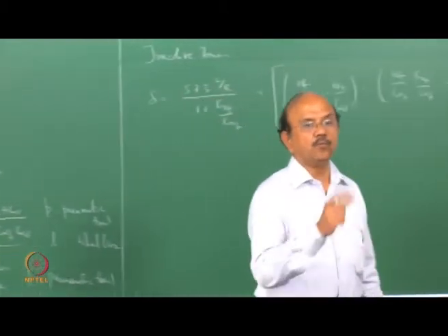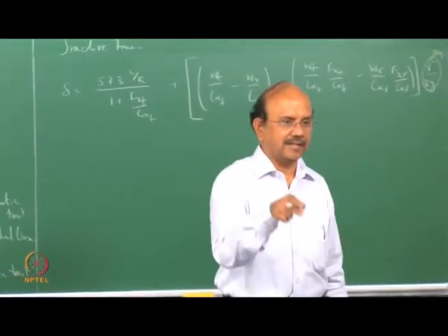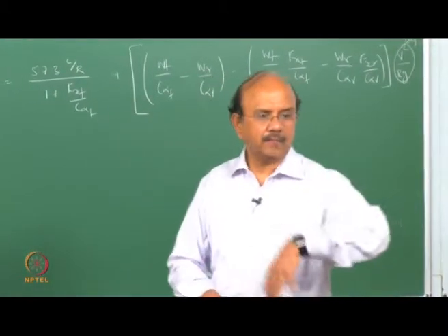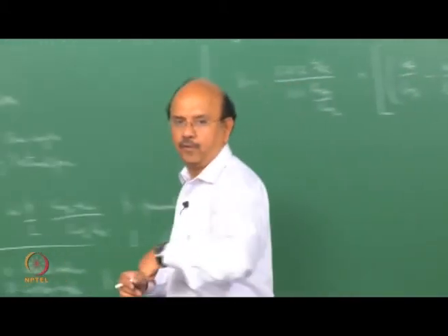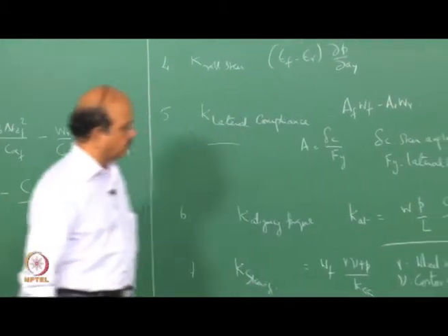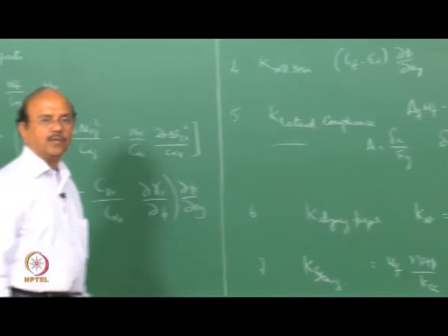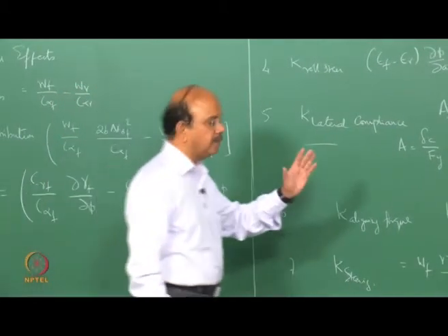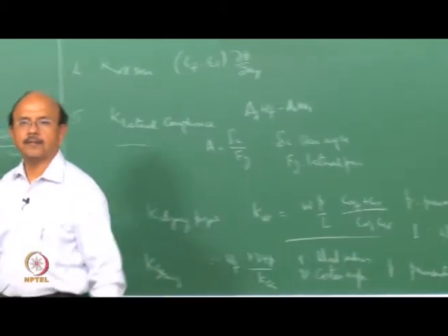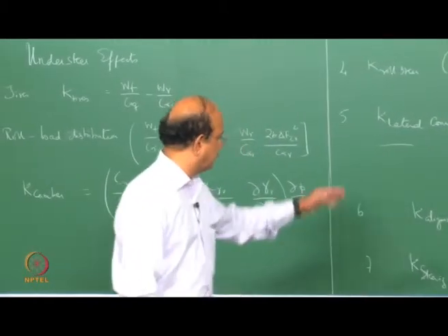So in other words, you have to give more delta. That's why it goes as an understeer, because of the aligning torque as the wheel becomes straight. So I have to give more delta in order to compensate for it, and that is the value for the aligning torque. Note that both P as well as C alpha F participate in this particular derivation.